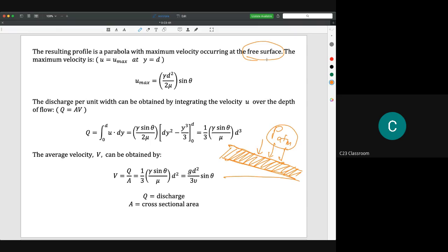Please be careful. For example, your normal pipe is circular in shape, so if you are calculating flow in a pipe, before you decide whether it is suitable for the flow in pipe equation or not, first you need to determine whether the fluid inside that pipe fills it fully or not.